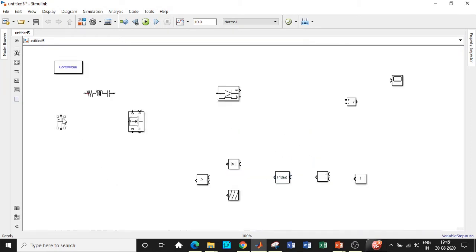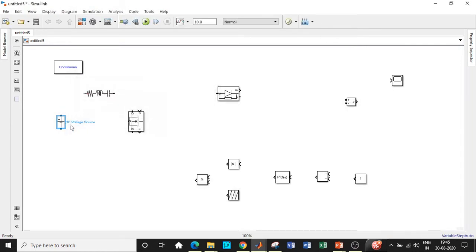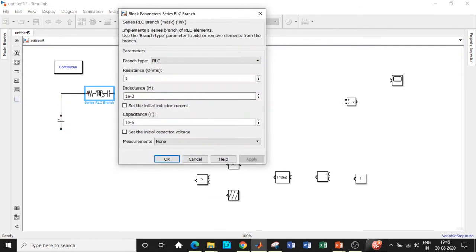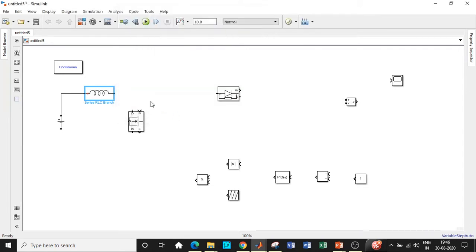All right, here we are. So we'll be entering our supply voltage, and the value of supply voltage is chosen to be equal to 15 volt. Connect it to this, and we'll be changing. Double click on this, and we'll be choosing an inductor over here. Choose the value of the inductor L1 to be equal to 35.62 microhenry. So enter E into 10 power minus 6 over here, and this is according to our design procedure. And once this is done, we'll be connecting it in this particular fashion.